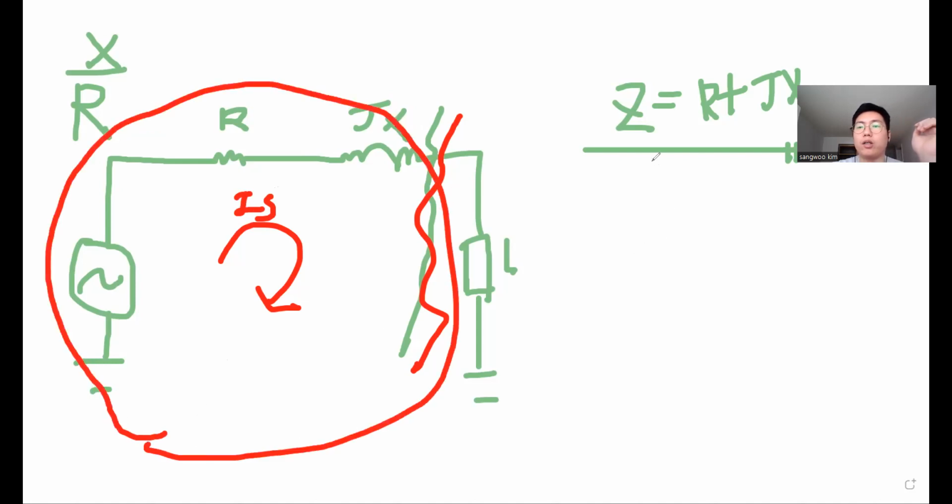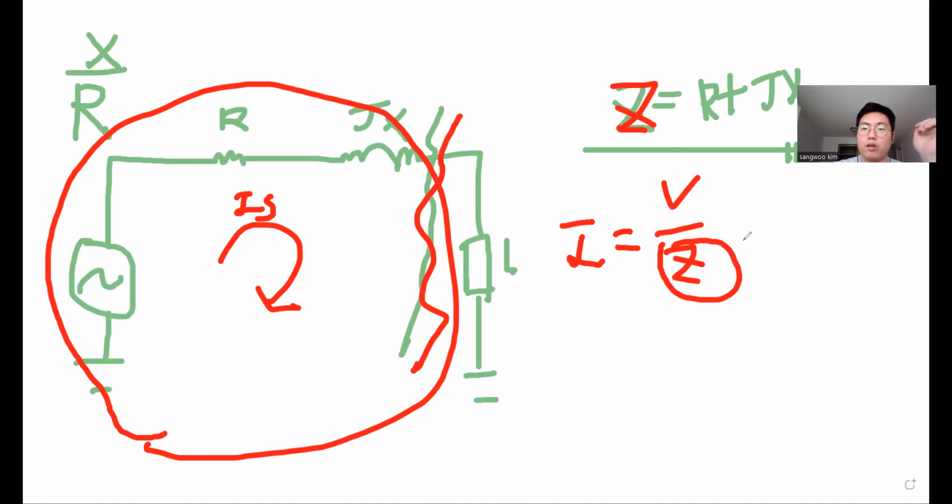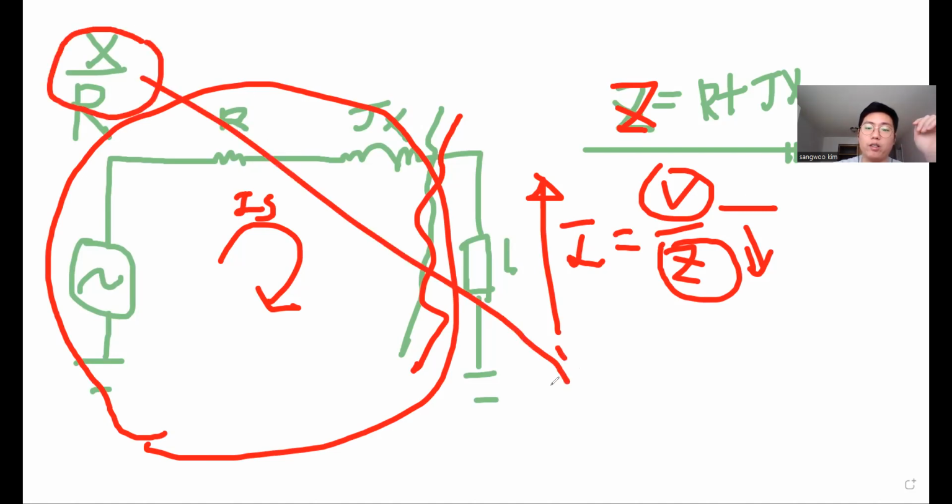But as you know, in the cable, the impedance is really low. So if we see Ohm's law, in the cables the impedance is really low. Which means we have this voltage system, and it's constant, which means this impedance is really low, so I is really big. That is what we call a fault current. But what I want to focus on today is the R/X ratio.